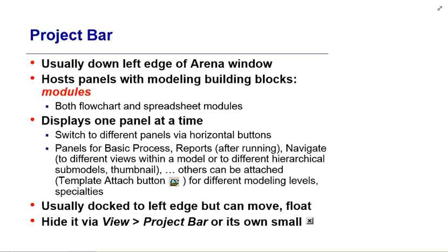And then finally, the reports window is the last window there. And that basically brings you into your reports module, where you can look at, after you've run your simulation, various different characteristics. Things like wait times, processing times, frequencies, number of entities through the system, size of your queues, resource utilization, and again, the user specified one, which would be done using the record module.